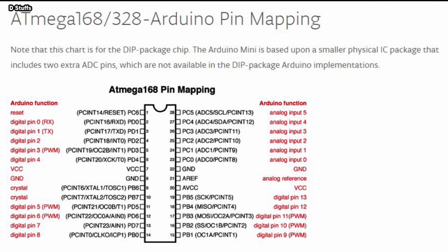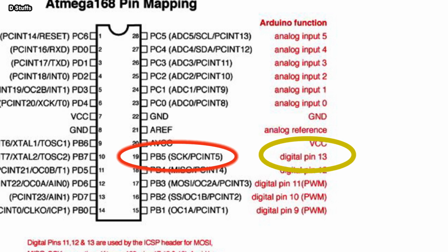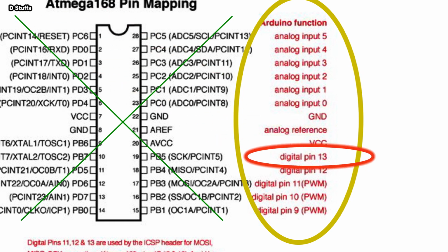Take some time to see it, and you will find out that digital pin 13 is equivalent to pin 19 of the ATmega328P microcontroller by Atmel, that is labeled as PB5, that is port B, bit 5. To expand the understanding, port B is 8-bit, and 5 designates bit 5 of that port. In Arduino, we do not care about the ATmega328P ports. What we care about is the function, such as digital pin 13.